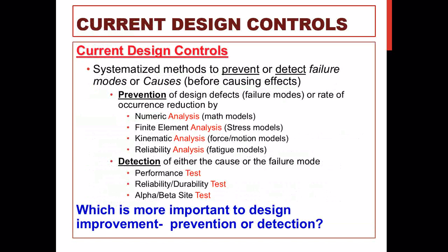You can see here we have other examples. For something that got loosened, maybe it was due to inadequate torque specification or an insufficient torque retention feature. Classic example, use of a lock washer versus a locking nut or a nylock nut could be key areas where the failure could come from. Current leakage, maybe we had a low resistance short, maybe there was poor insulation involved. Fractured welds, maybe it was due to low strength welding material, maybe it was just an insufficient number of welds used for putting the product together.